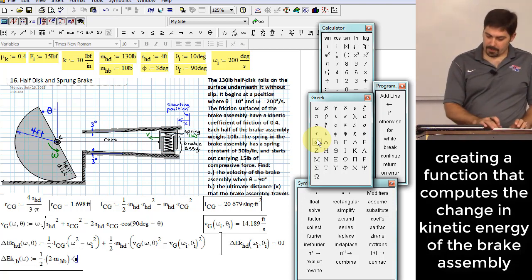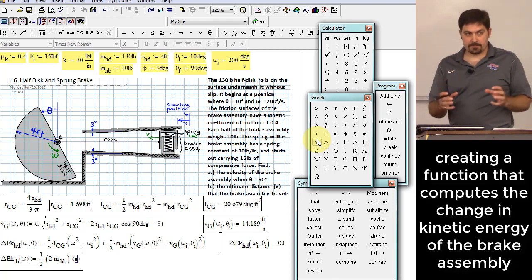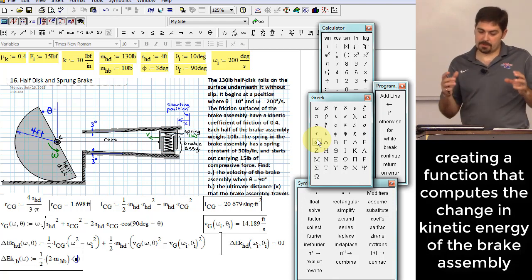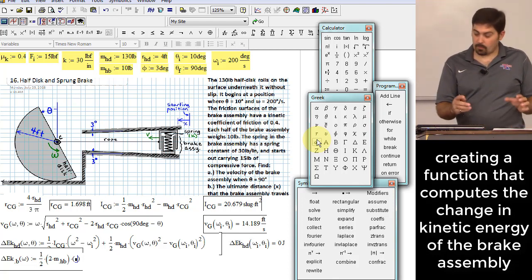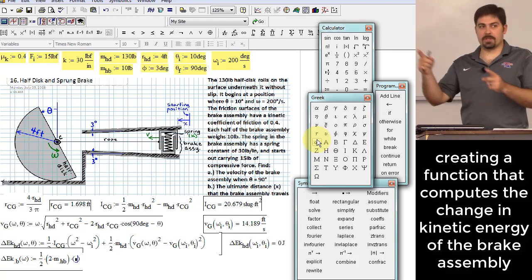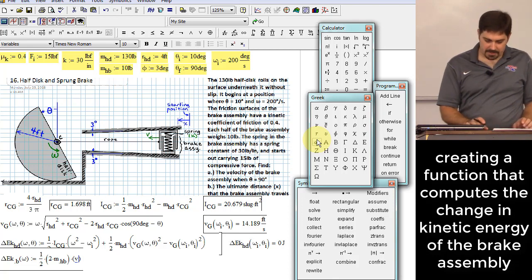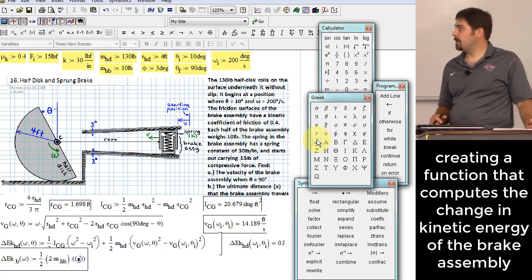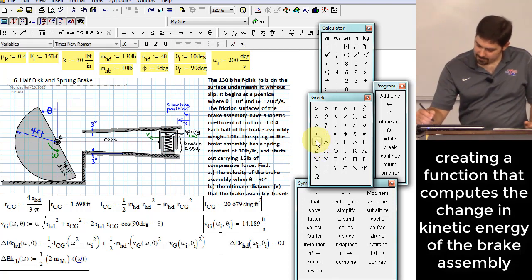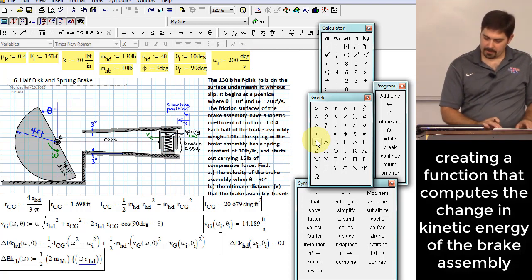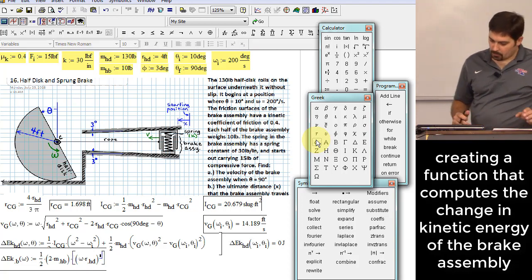All right, well, for the next part, we need to have the difference in the squares of the velocity of the part for the 2 different locations. So we'll start with what it ends up with, and subtract what it started out with. Here we do VC, but I don't think I made a separate function for that. Let's just punch it in here directly. So all I need to do is omega times R sub HD, according to what I put on my written sheet.